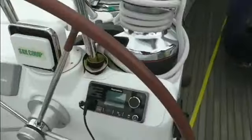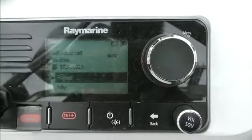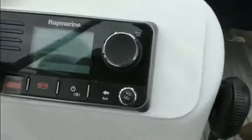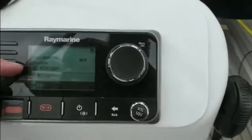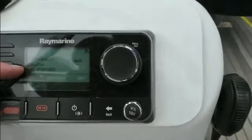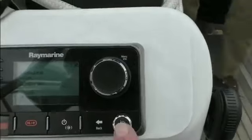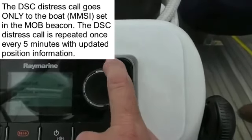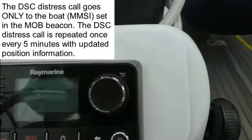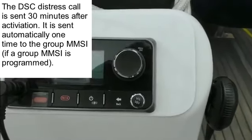There it is right there. It's alarm. It is sending a routine call to the Raymarine radio. Okay, so that's our Raymarine call, and we're going to look at the information. You can see on the top here, it shows the MMSI of 972603-921, which is the MMSI of this device. And we can see it was a routine call from that. It does not provide us any position information, nor did it alarm the navigation system or the distress alarm on your radio.